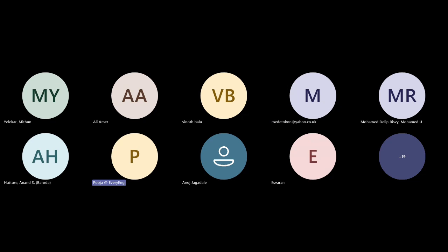The failures which occur during operation can surely be avoided when you design a component. But when I say I have to design, I'll come to a very basic thing. I want to select a rating of a flange. I know the design pressure, I know the design temperature, and accordingly I will select the rating of the flange. But when I make a mistake there itself, selecting a lower rating instead of the higher rating, this will be caught when you test a system. Before commissioning of a plant, the complete plant will be tested. There you will come to know that you have selected the wrong rating or you have done the wrong design.